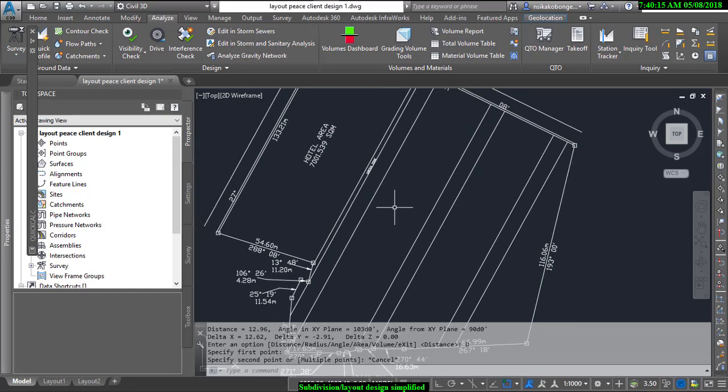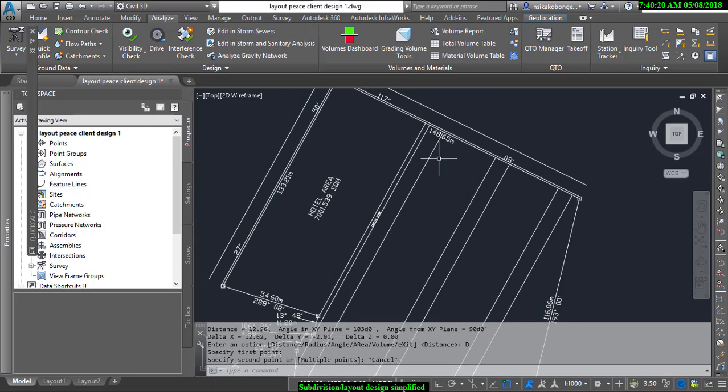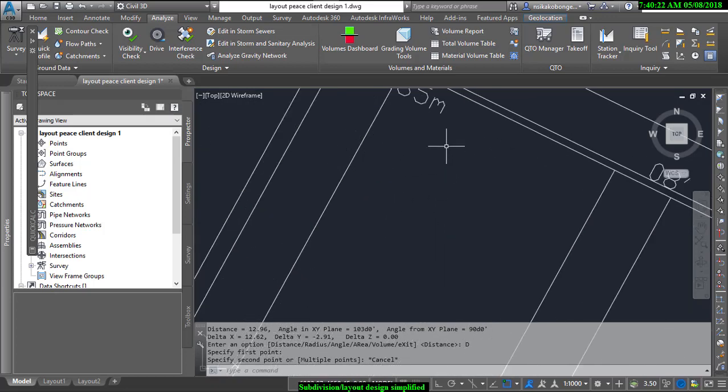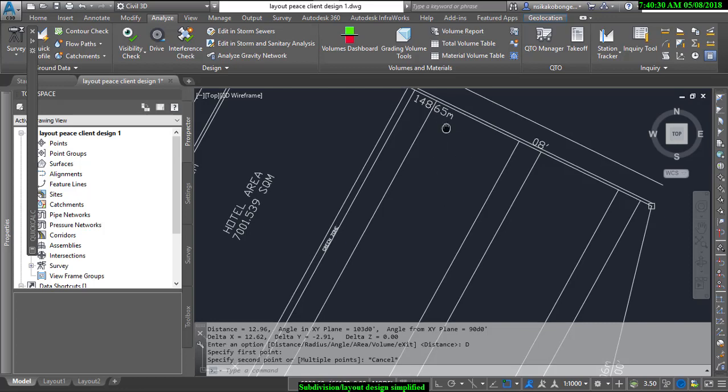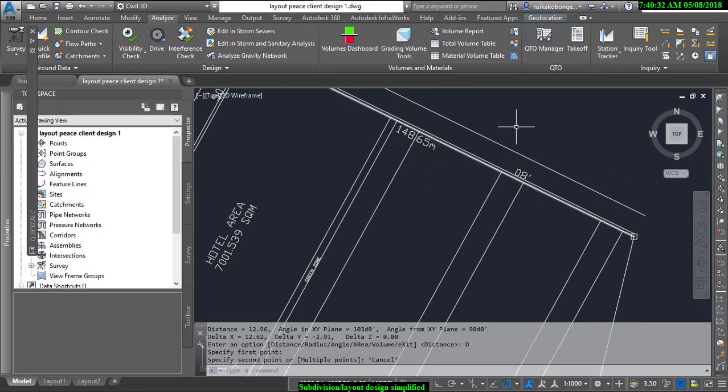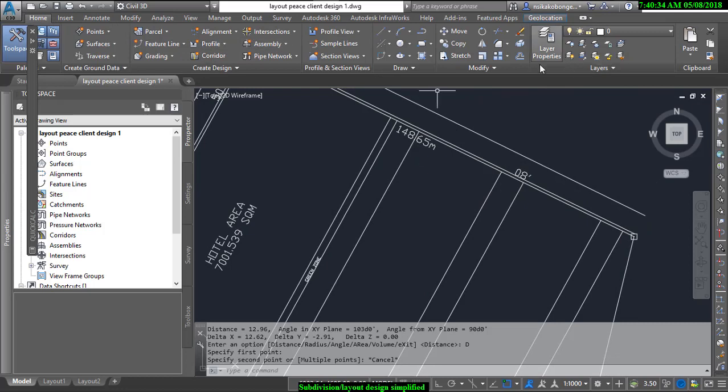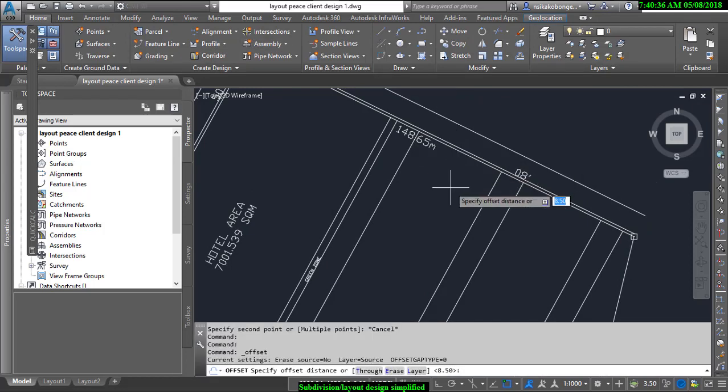All right, so let's continue. I want to check out the number of plots that will come in here, and make sure that when you're working, the angles must be at least 90 degrees, or 70, or 60, where it will be easy to set out on the ground. That's what you should understand. That's one of the basic concepts of lot design.